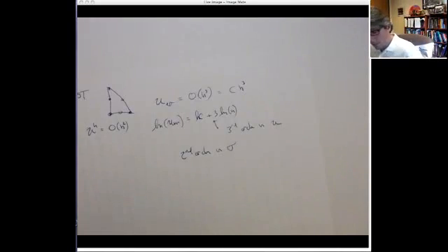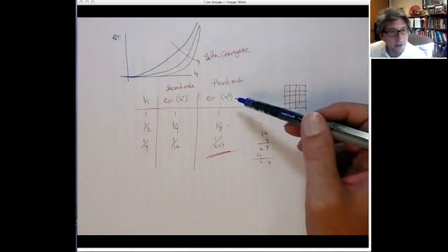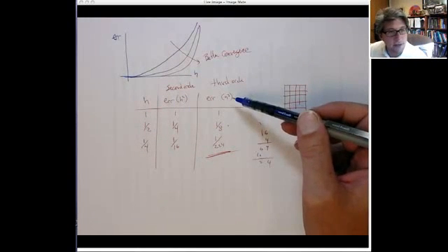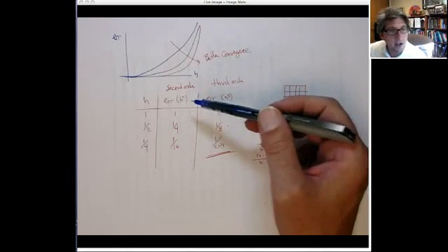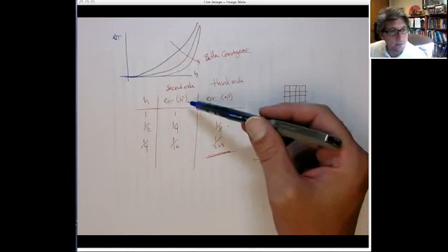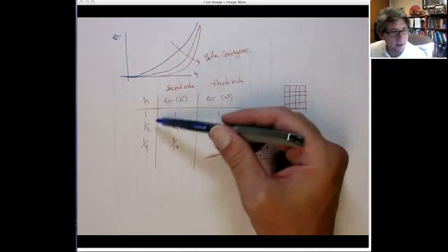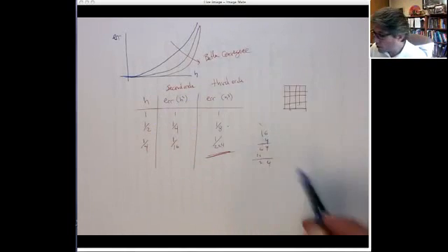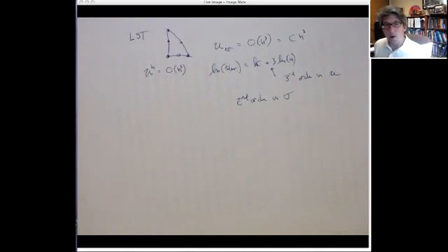And you can see from what we had before, from these, how dramatic a difference you can get. So the linear strain triangle and displacement is here, and it's here with regards to stress. The constant strain triangle is here with respect to displacement, as opposed to here, and it's here with respect to stress. So you can see how you converge much better with the higher order elements.